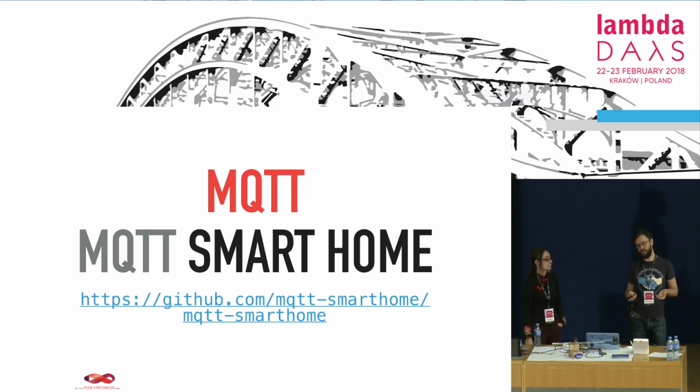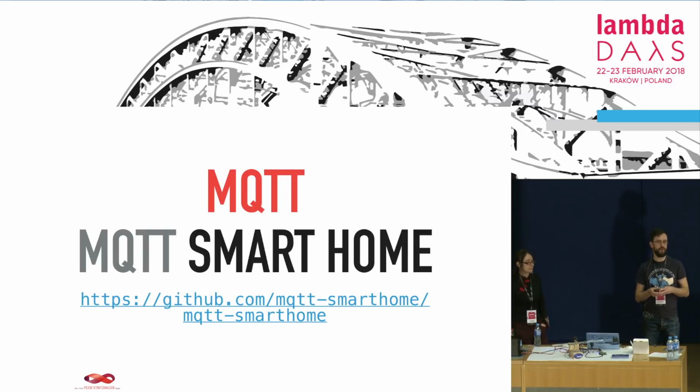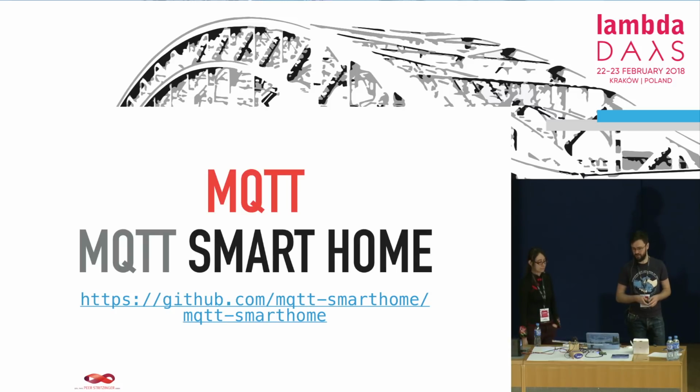So for example, one of the applications they list in this smart home repository is a bridge from Apple HomeKit to MQTT, which means if you had MQTT running and you had the GRiSP sending MQTT events, for example, with these temperature values, you could then view this via Apple HomeKit on your iPhone or something like this. And there's lots of different projects for different hardware and different GUIs and frontends for things. So this is very cool stuff. And we also plan to use MQTT for some more industrial applications as well, because it's a very nice protocol for distributed systems in general when it comes to automation.